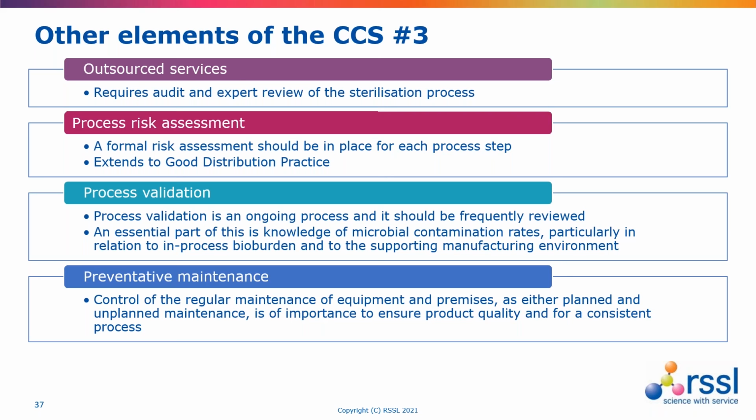And also process validation needs to feed in, because we need to understand what parameters we could adjust, not adjust, how do we measure drift, and how does that loop back to the original validation. And we also need to understand things like hold times and the impact upon the potential for microbial growth, if there is a bioburden present. So there's a number of important elements there as well.